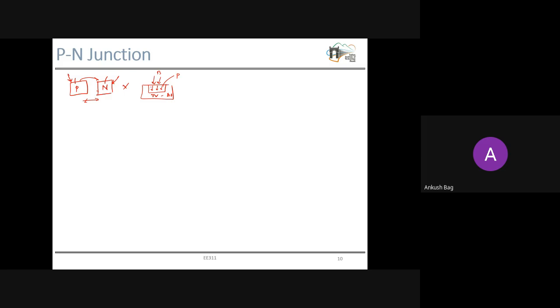So this top layer is now converted from n-type to p-type, because here the majority carriers will be holes. This way we are fabricating the PN junction, because now at this interface, on one side we have p-type semiconductor, and on the other side we have n-type semiconductor.